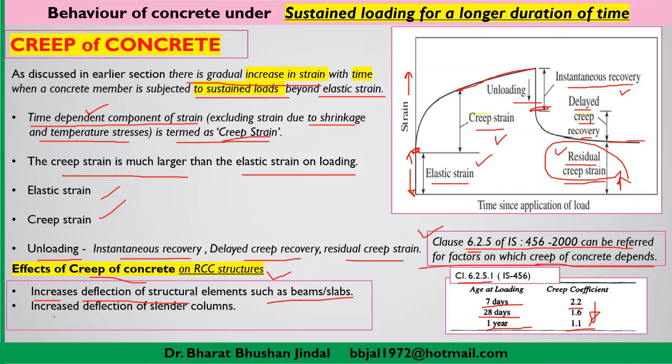It will increase the deflection in slender columns. As well as when we talk about pre-stressed concrete, which is not currently in our scope, but just for the purpose of knowing the information, there will be some loss of pre-stress in pre-stressed concrete due to creep. So that is why creep is a very important factor which we have to understand before designing any RCC structure.